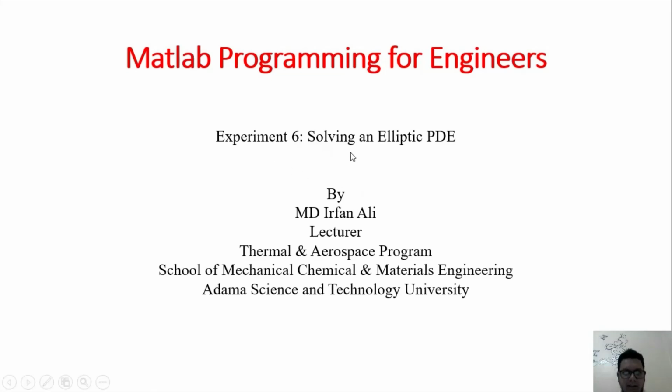Hello everyone, in this segment we will learn how to solve a given elliptic PDE in Matlab software. In this lecture I will introduce you to a graphical user interface known as PDE Toolbox. PDE Toolbox is a graphical user interface of Matlab software where you can do physical modeling, where you can draw the geometry of your problem and you can solve the given elliptic partial differential equation using finite element method.